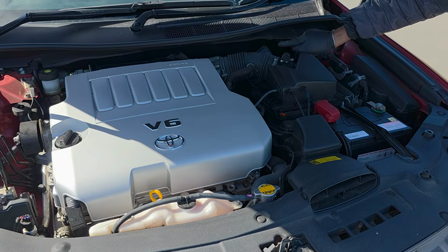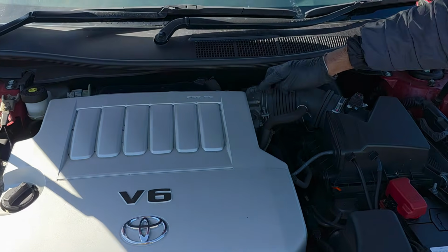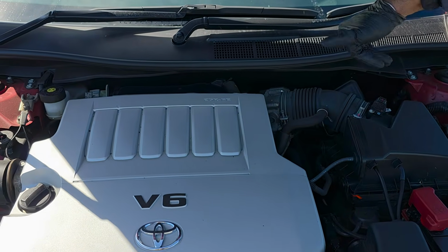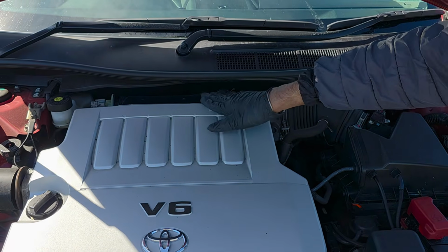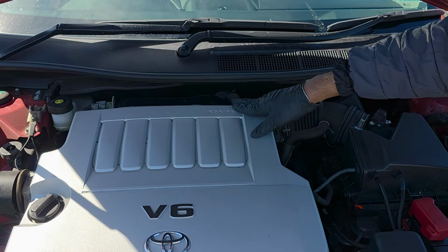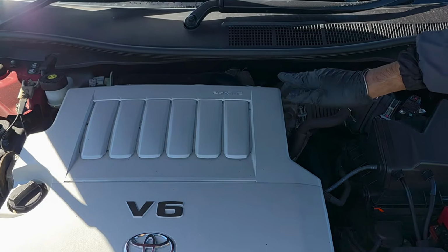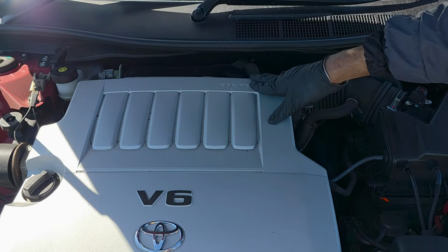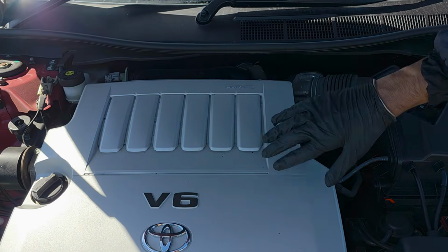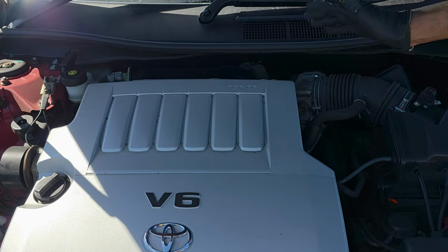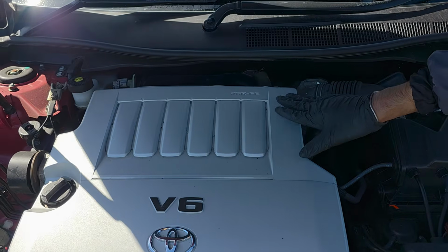Now this is the mass airflow sensor. If you go further down, you will see you have got your throttle body. This throttle body is the plate which actually opens and closes, and lets air into the intake manifold. Your intake manifold is right here at the back, and your manifold absolute pressure sensor is mounted to your intake manifold, so it determines how much air is actually going into your intake manifold, and based on that data it will send signals to the ECU to either send more air and less fuel, or less air and more fuel, depending on the live data.